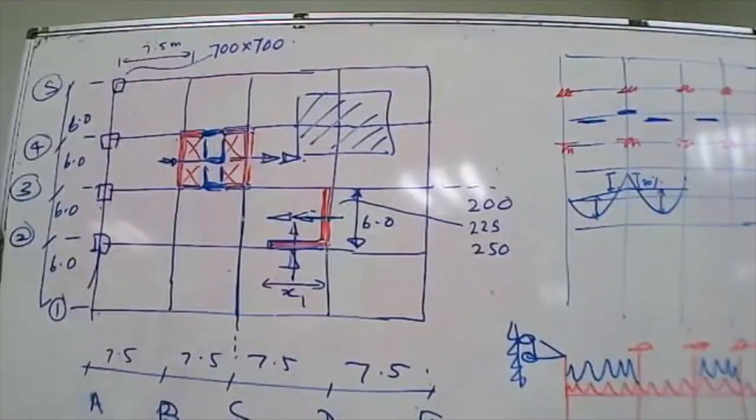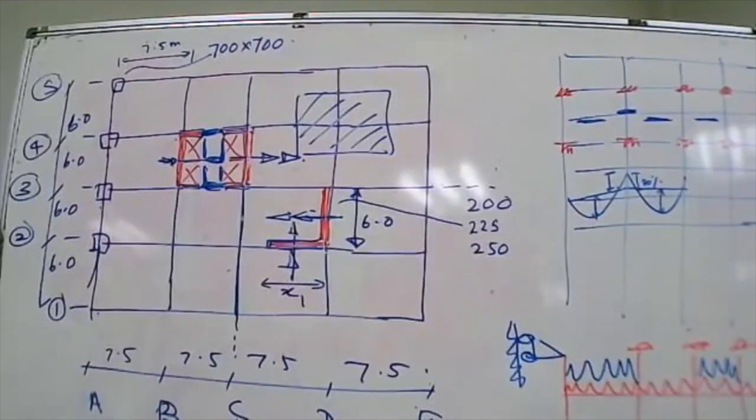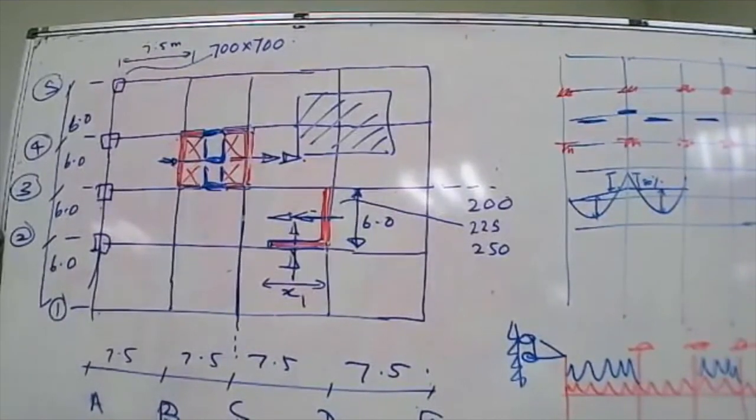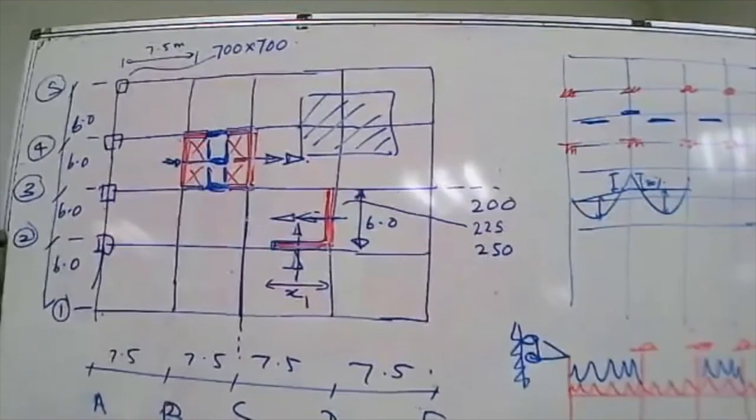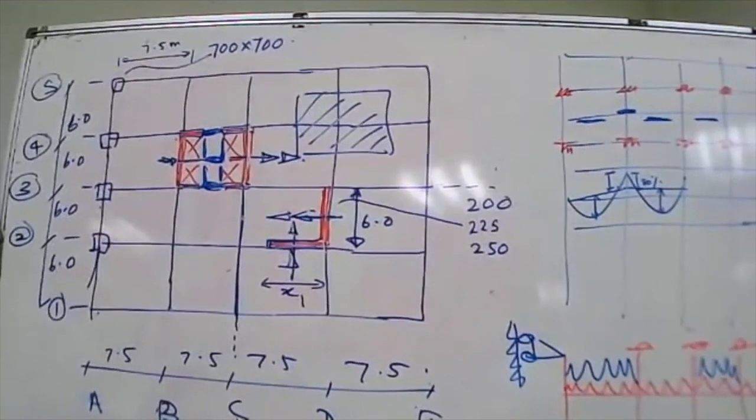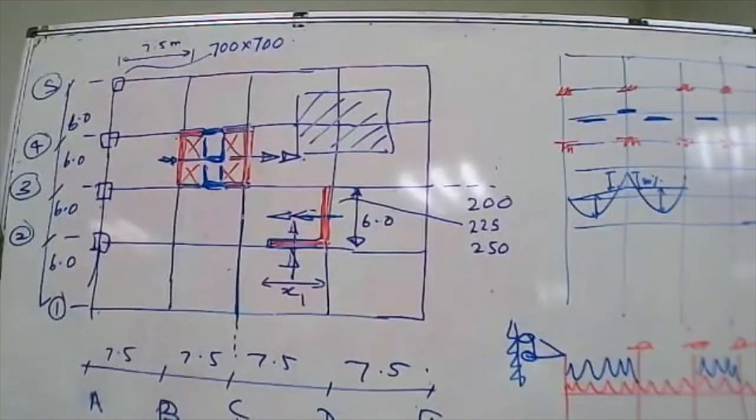In a 10-story building, it's not worth trying to make the columns too small, because even the smallest column you can have will be only about 500 by 500. So you have to change the shutter and do many things, and I really don't know whether it's worth it. The same question is in the chat box, so since you answered the previous question, that covers it.